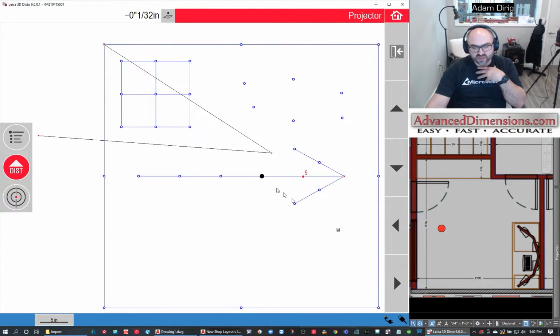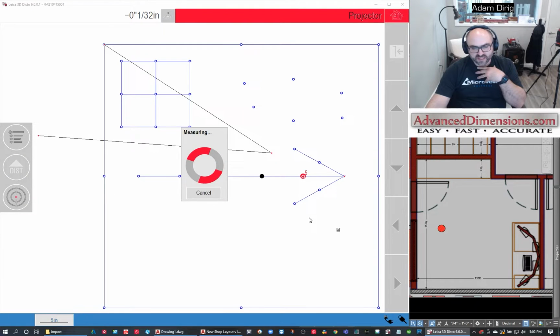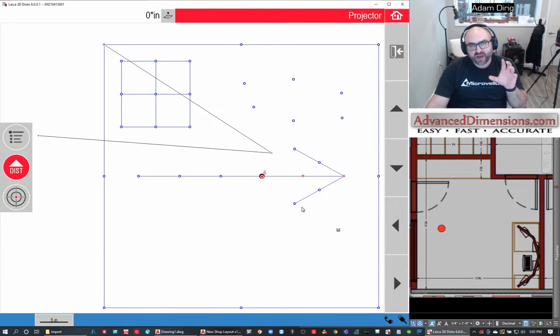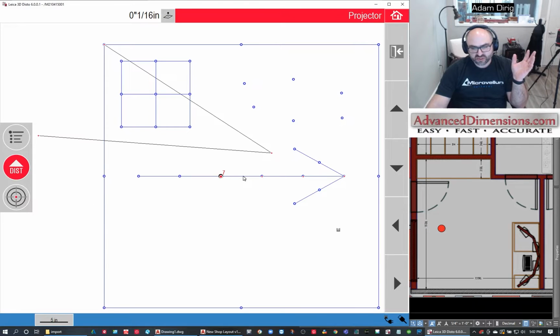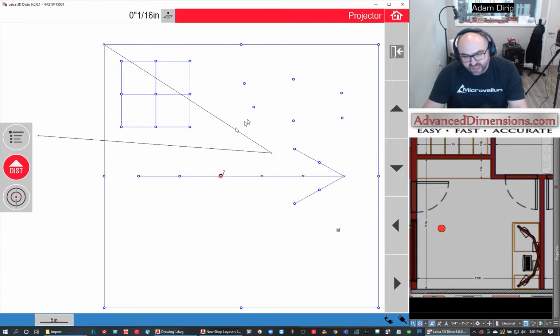We can use this too and use that to move around. The little remote control that comes with it is another way to use this projection feature. The arrows act similar to this. So we can keep going. And as we go, we're just projecting these points every 6 inches or so. And we're seeing exactly what's happening. And we just literally go through the motions with everything here. So all that drawing came in. I'll see all these points that I did randomly, see everything else. So this is the way that you would use the projection function with the 3D Disto.